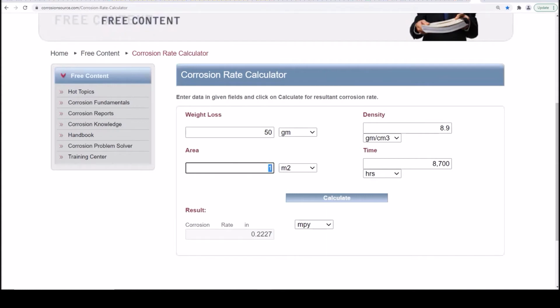So ideally you want to be at 10%, so that's 500 grams. That's why that number, 500 grams, is pretty typical. Now, if you double your corrosion rate to 0.4, then 500 grams turns into 20% a year. You want to get to about 0.2 MPY, which is possible. That is very, very possible. That is what you will find on these machines.